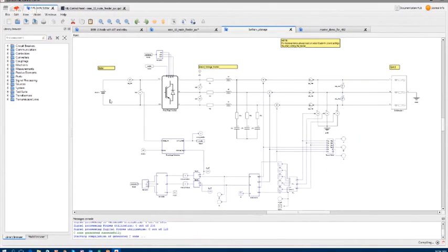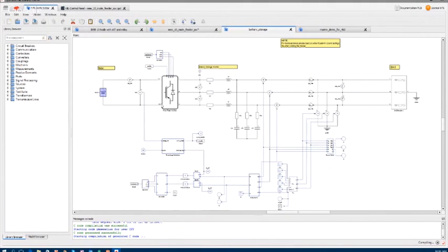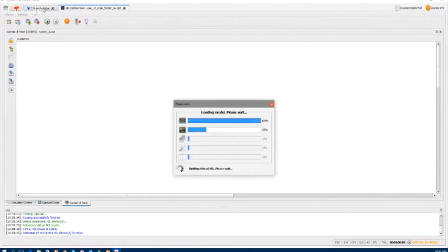This is a battery storage converter. You can see here the battery model, again, that is coming as a part of the library. As with all other models, this one is also customized only through the technical spec. So even for battery models, we have some predefined battery types, nominal voltages, etc. This is how we are designing the curves of the battery. This converter is going to be controlled through an internal modulator.